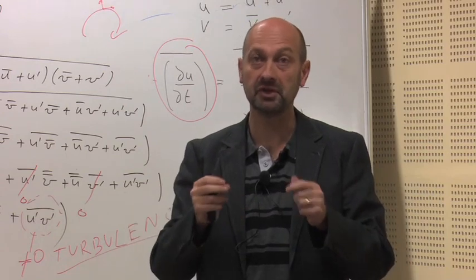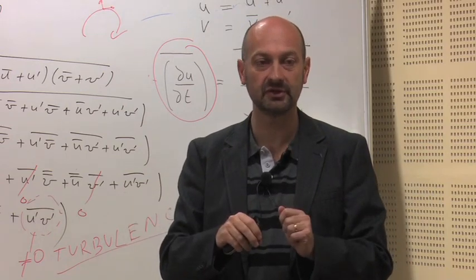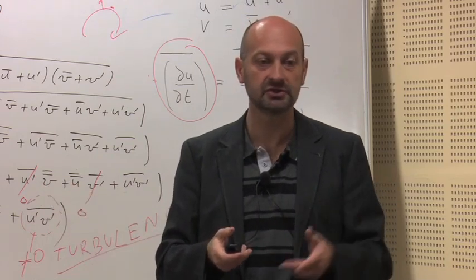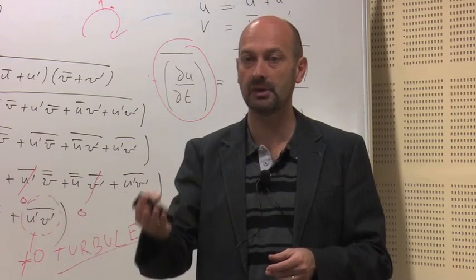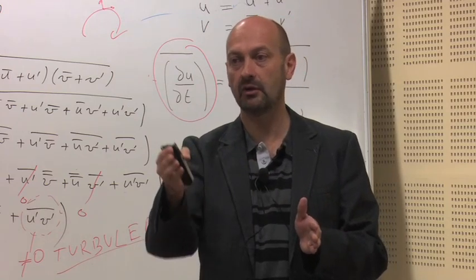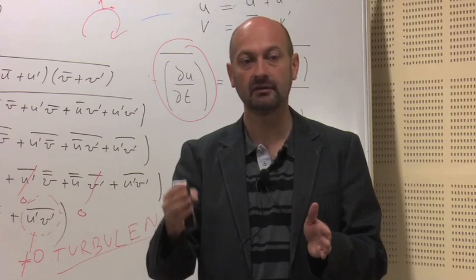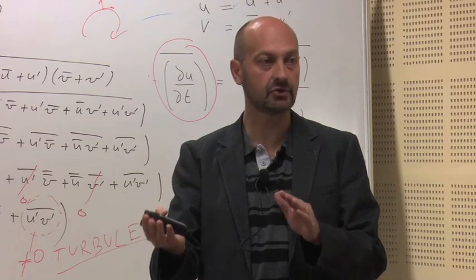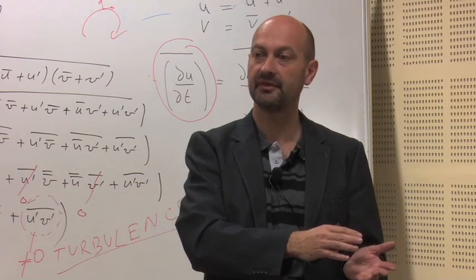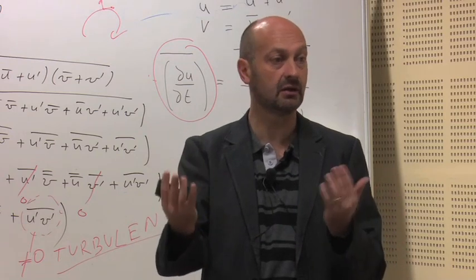You are going to assume that you know the physical properties. For example, you know that the viscosity is 1 point something, but actually it's not. So you are facing all the problems when you want to compare experiments with theory or with CFD. And then you might have errors coming from CFD, but you might have errors coming also from experimental data. So you have to be critical when you do that.